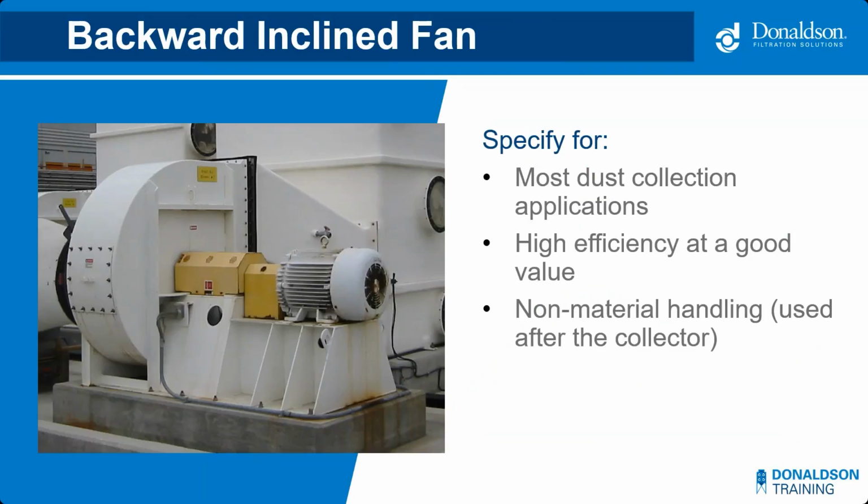So here's one of my favorite pictures. This is just a textbook fan installation. This is a direct drive fan mounted to a nice concrete slab. It has inlet and outlet flex connections and is really just a great picture of what we want to do in the field.